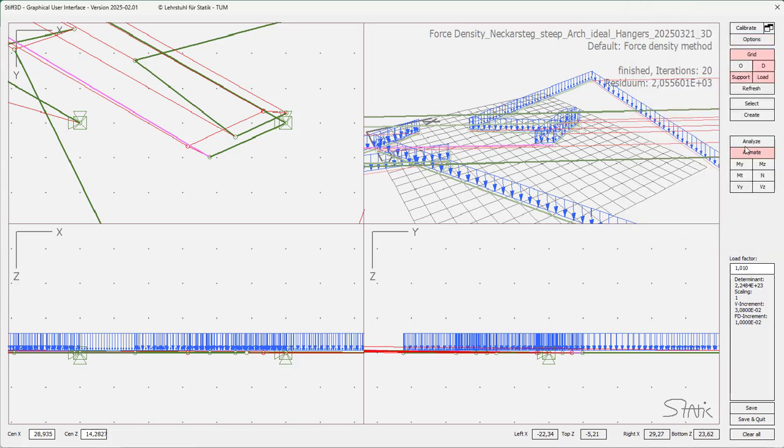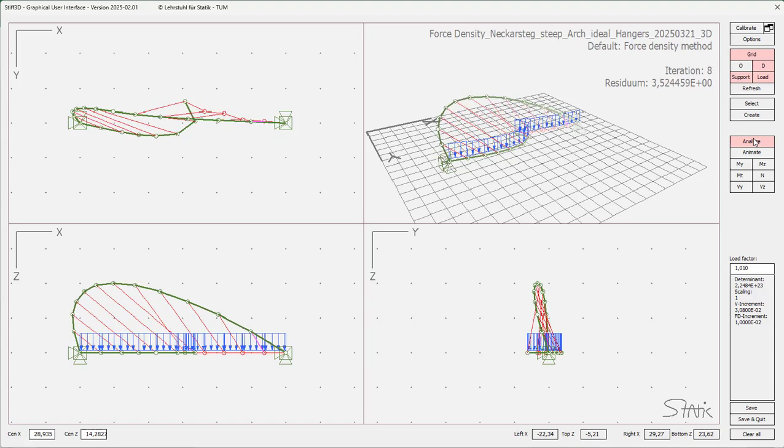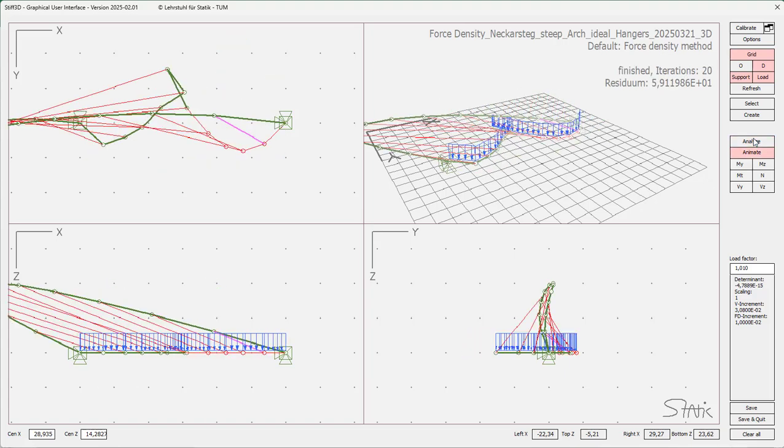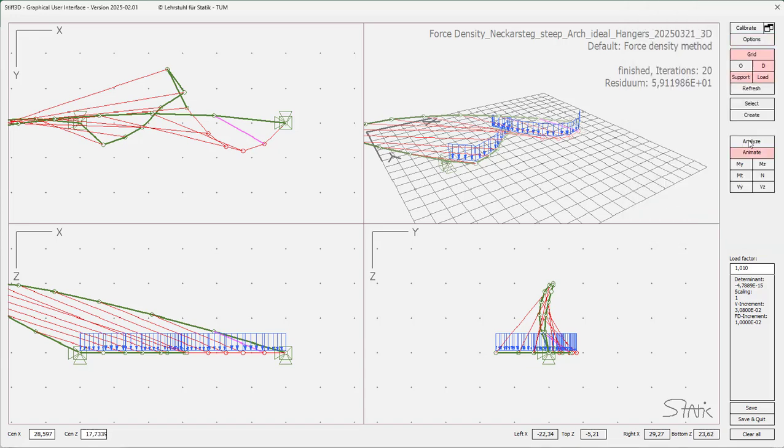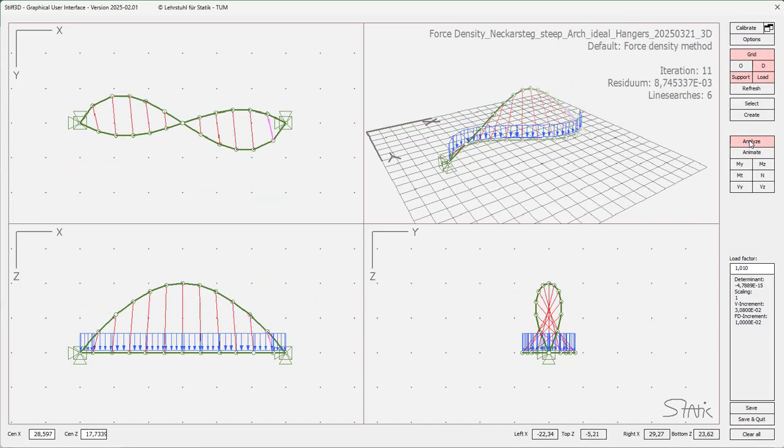This makes it possible to modify and directly optimize on the augmented Lagrange function. You see we have stabilized the convergence of the problem a little bit, but not completely successfully. We add some line search options with another penalty factor. I know that 10 is a good value. We can try it with 10 here and see what happens. It converges to the proper solution that we would like to achieve in 12 iterations together with 6 line search.